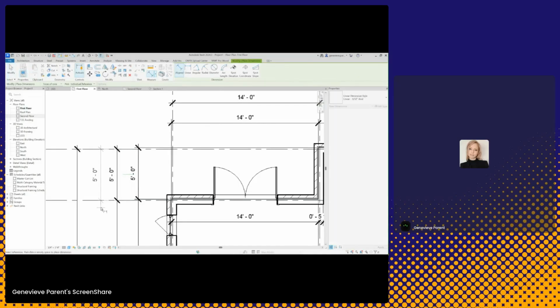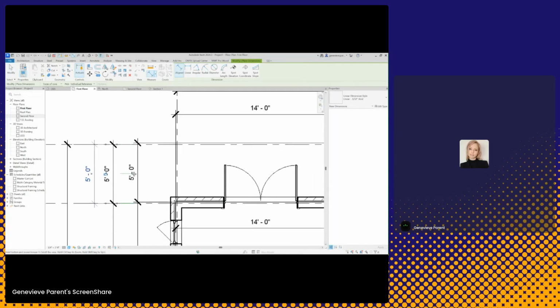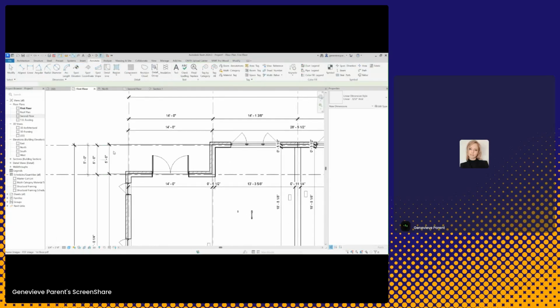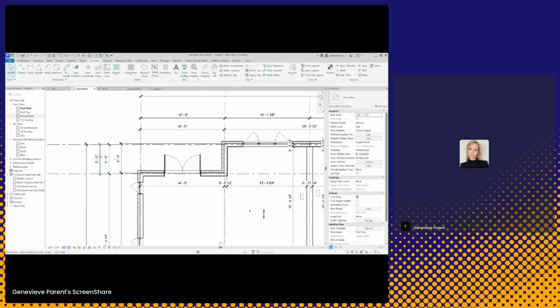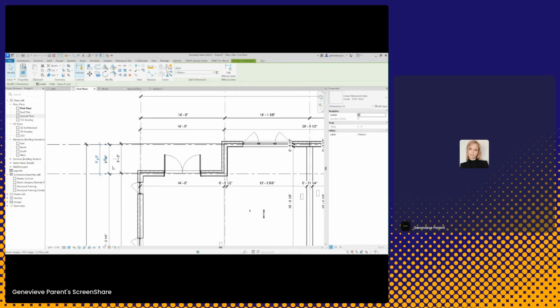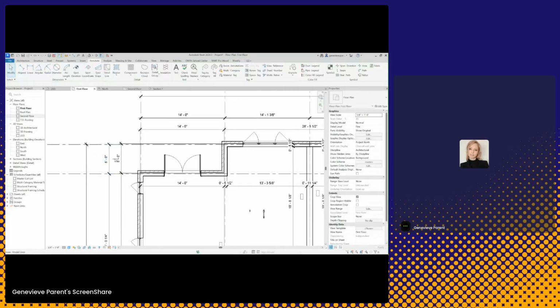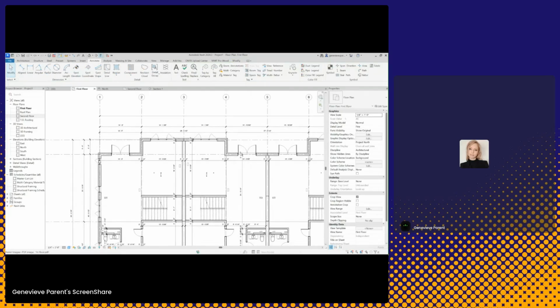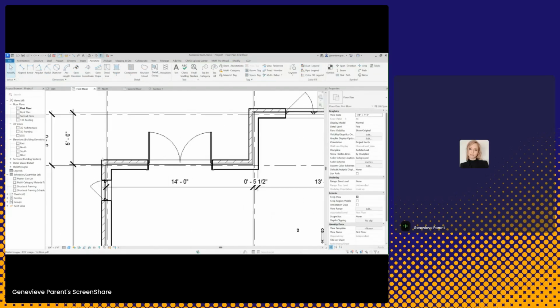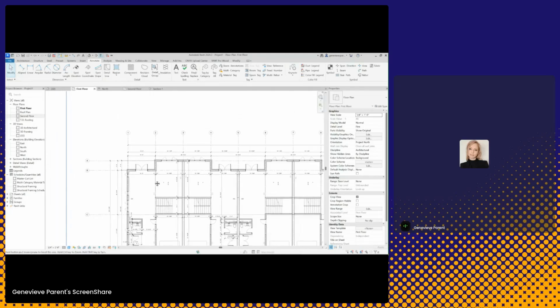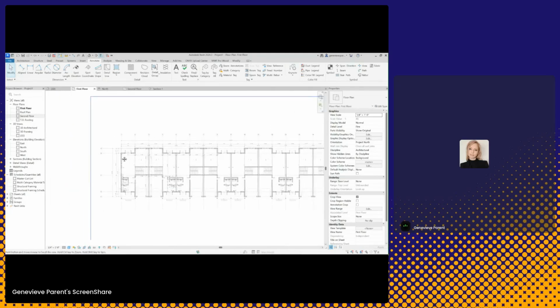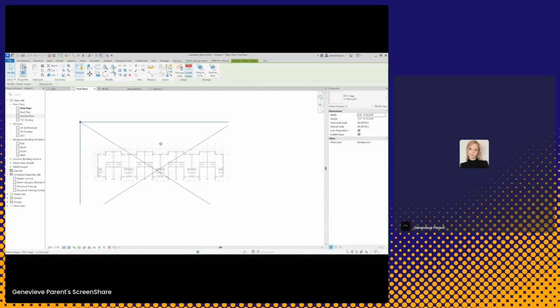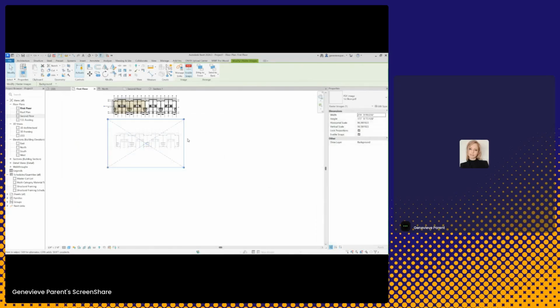It's a little bit tricky when you're drawing over a PDF. It's not the best method, but it is a method that can make things faster. You still are going to have to do some adjustments to make sure everything works with the actual dimensions of your plan, because there might be like 1/2 inch, 1/4 inch difference. It's not going to be 100% perfect. DWG is probably going to be a lot more accurate. I would recommend a DWG for sure.